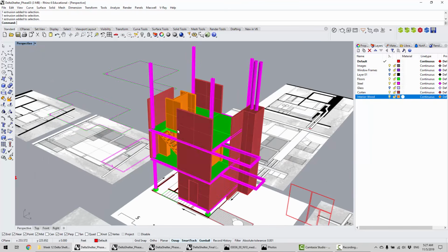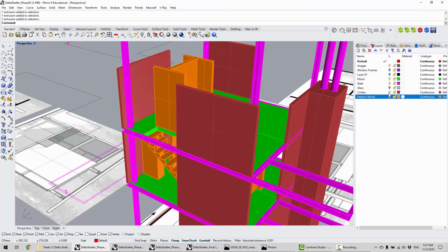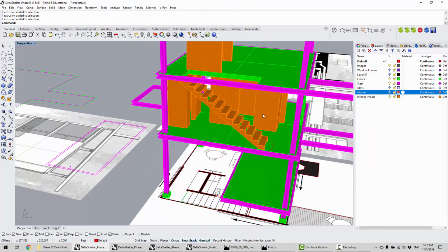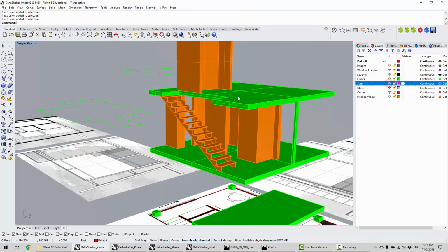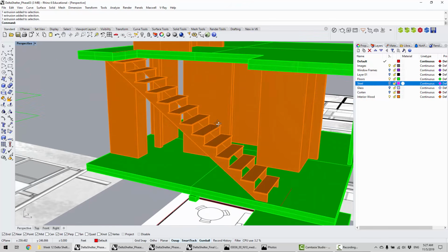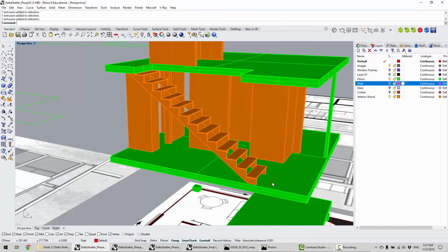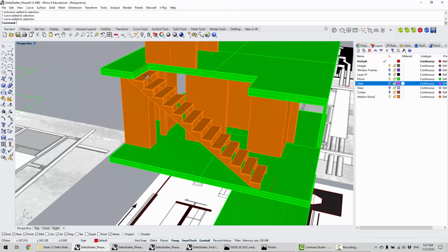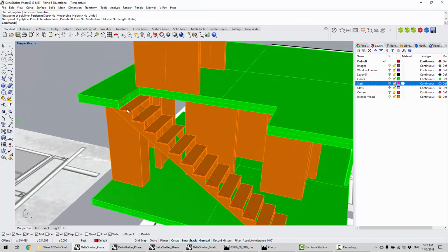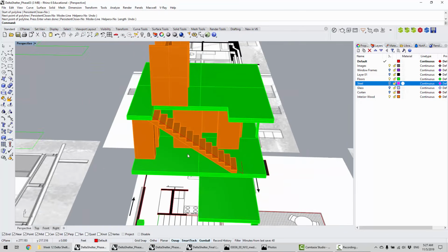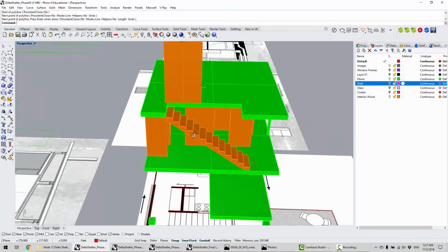All right, so one big question you might have is actually these stairs, right? So like I said earlier, the way I typically deal with this, and you can close things down so it's less in the way, is that you've got to figure out the first line, which is where the stair slope starts and then where it ends. So it's up there, right? So that's its trajectory. And what I do is draw a line from one corner to this corner, right? I count the number of stairs that are in here. I believe it was 14 or 15, right?